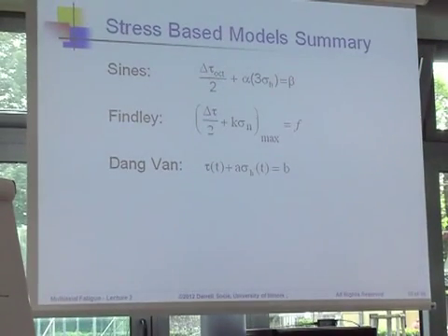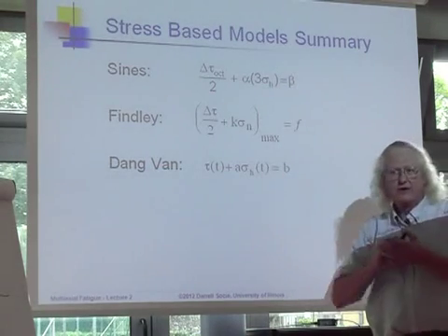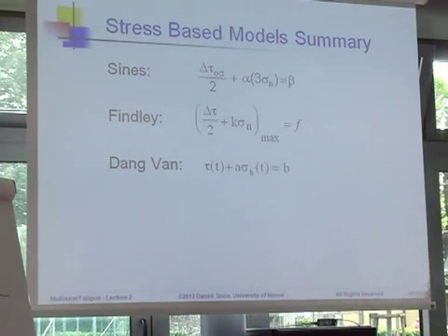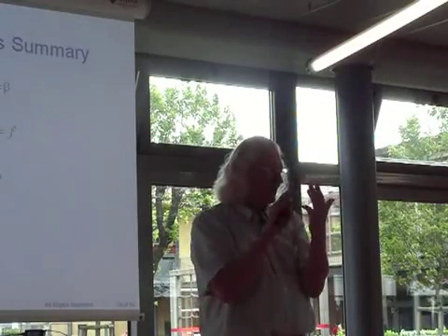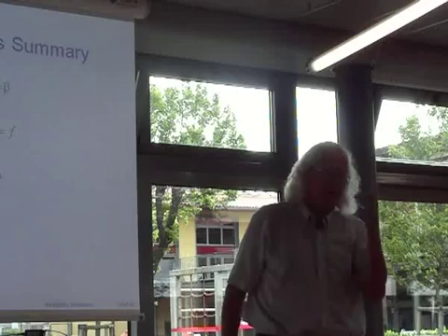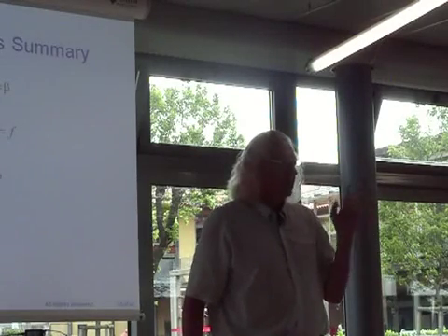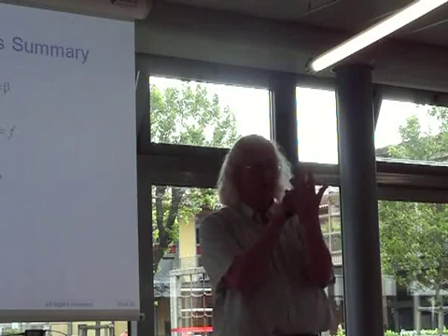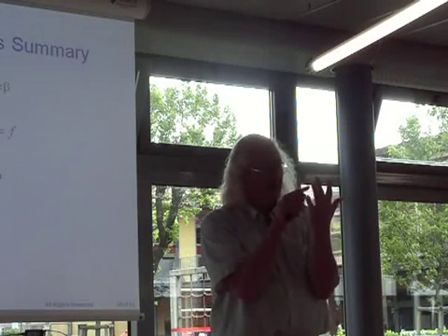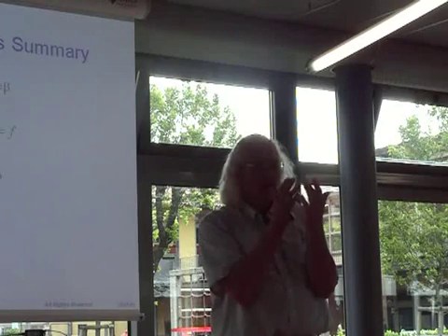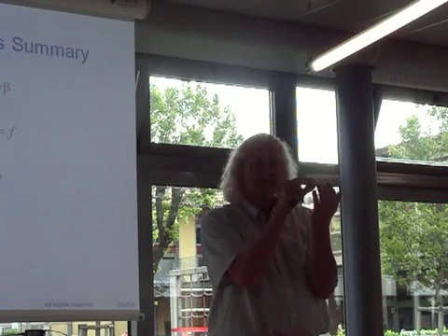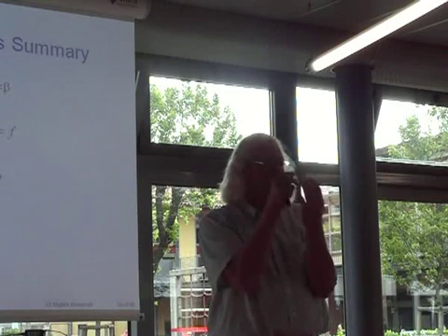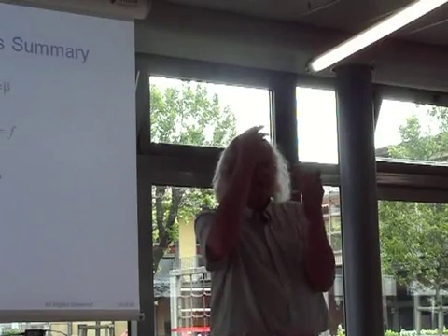But at the end of the day, let's just compare these three ideas. So you remember, we really have three conceptual ideas for the fatigue theories. And as I mentioned when I started, all the other 100 models out there, I can probably put in one of those three classes. Sines was completely empirical. I did the experiments, and he just found some math that matched it. No critical tests. Findley's was based on this idea about cracks and normal stresses helping open the cracks. That was his physics. And Dang Van's idea was based on the physics of hardening of an individual grain, essentially plasticity in it.